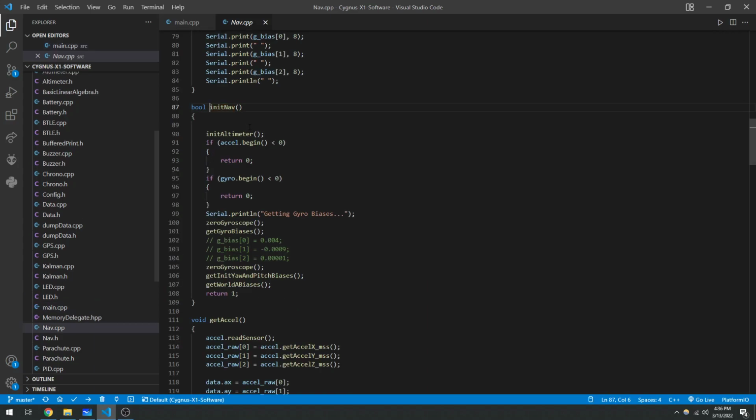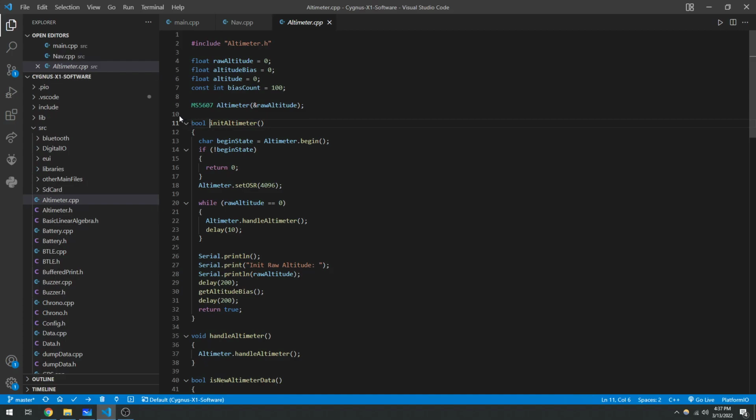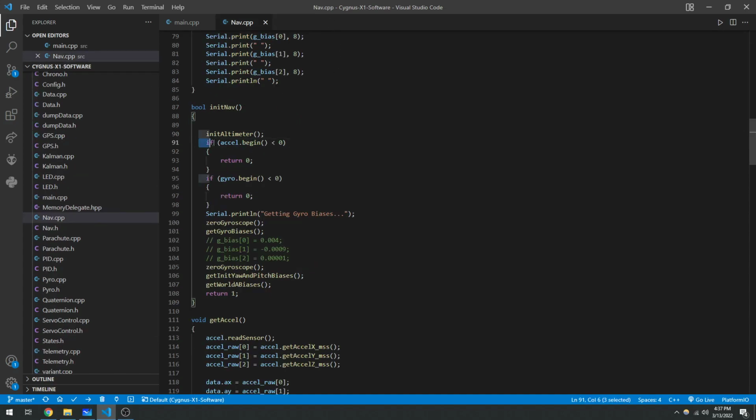So initialize navigation, and this is the thing that takes the longest. This initializes the altimeter, which first starts it up and gets the altitude bias. It looks like it takes 100 measurements here, and it averages them out so that we can get our zero altitude. Then there's accelerometer begin and gyro begin. This is where we also zero the gyroscope. We get the gyro biases, and we zero the gyroscope, I guess, again. Don't know why we do it twice, but...